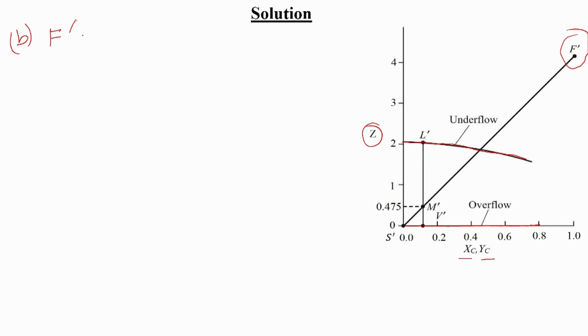So, out of this we can say, if we remove this inert solid, only 19.5% solubilized solid is there. Then it will be 1000 into 0.195, that is 195 kg. So this is F prime, 195 kg, which is simply kg non-solid.